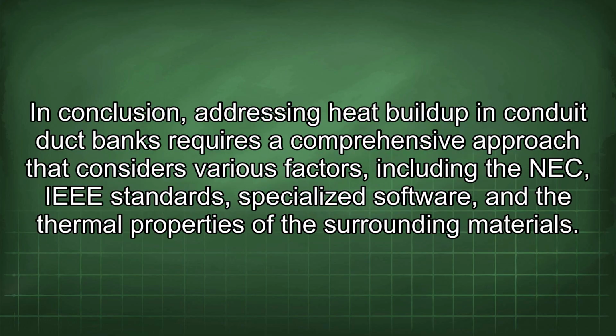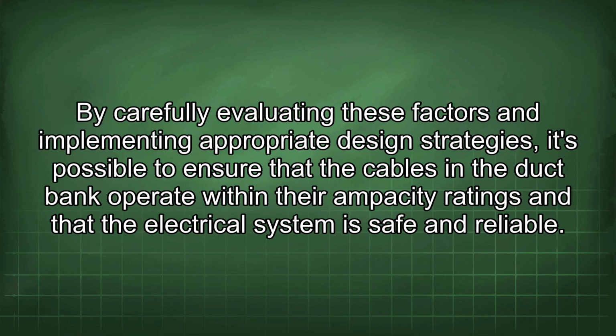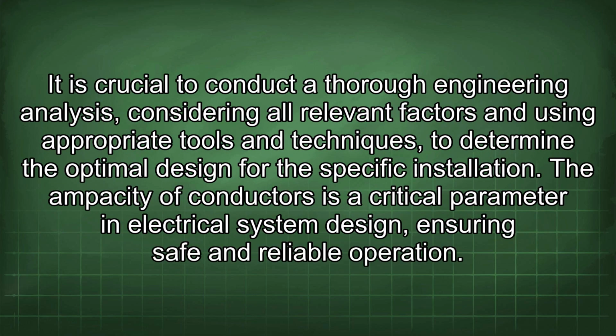In conclusion, addressing heat buildup in conduit duct banks requires a comprehensive approach that considers various factors, including the NEC, IEEE standards, specialized software, and the thermal properties of the surrounding materials. By carefully evaluating these factors and implementing appropriate design strategies, it's possible to ensure that the cables in the duct bank operate within their ampacity ratings and that the electrical system is safe and reliable. It is crucial to conduct a thorough engineering analysis, considering all relevant factors and using appropriate tools and techniques to determine the optimal design for the specific installation.